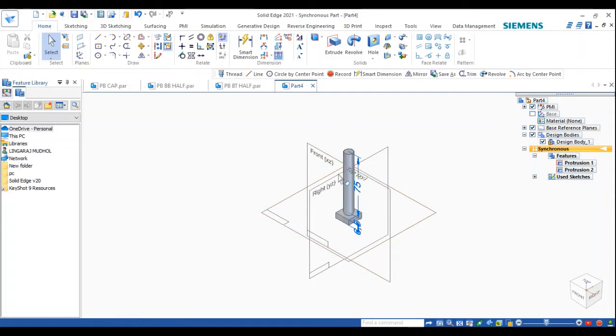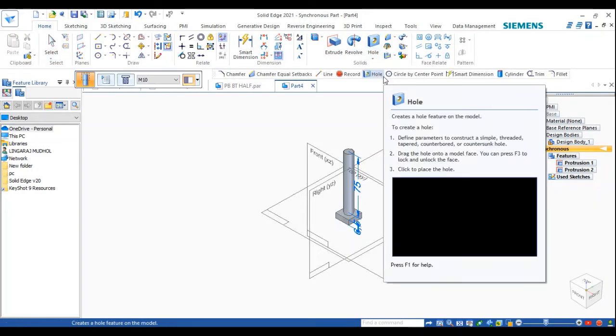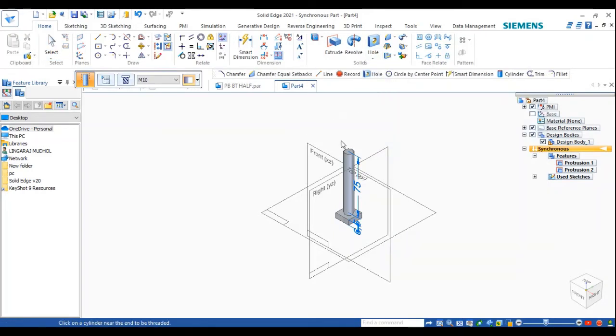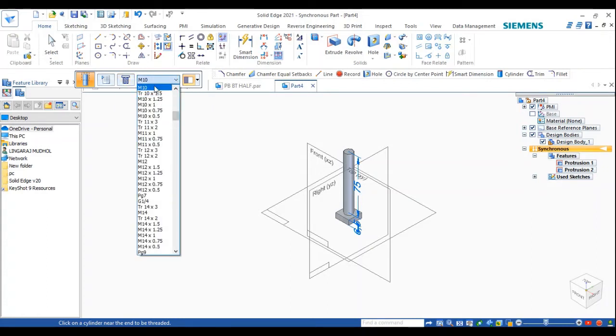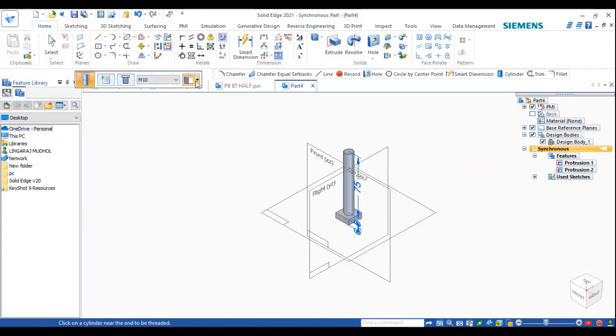Okay, again for the bolt there will be a threading, so there is an option called thread here. Based on the threading, there will be many types of threading. So they are given it as M10. So we'll select the M10, and here we should do only a 26 mm threading from the starting of this position. So it should be a finite.